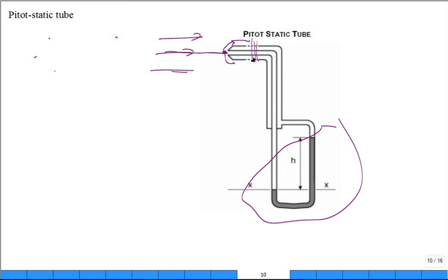Okay. Then there's a sequence of holes that are a little back from the tip. Right here they are on this one, and they do a pretty good job of measuring the average pressure around there, because they let the air in through the holes, and they come to the other side of a manometer, a pressure measurement device. Typically they're little digital manometers. Okay, so you hook up to this edge and that edge, and this is to line it so you know where your alignment is. So you hook them up to there, and now you could have a fluid manometer, or you could have a little digital readout, and you could then measure the pressure difference between the two.